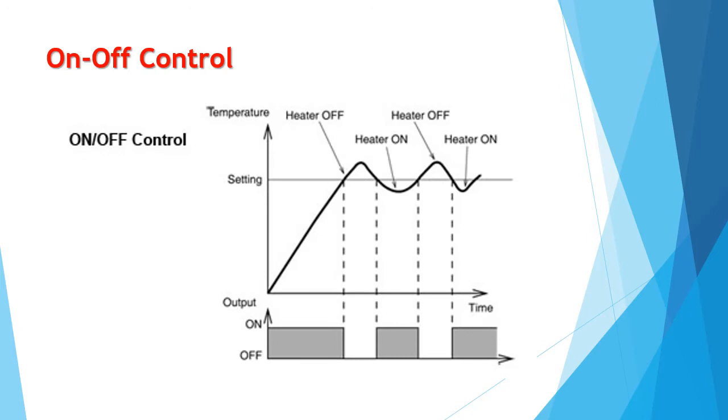Now let's assume that the set point temperature of the oven is 120 degrees Celsius, and the initial temperature is 0 degrees Celsius. When activated, the controller will sense the temperature difference via the temperature feedback and switch on the heating element. The rise in temperature is not abrupt but slow, and it takes around 300 seconds until the temperature reaches the set point value.